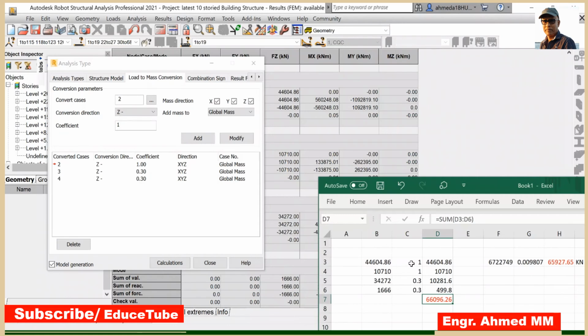This one is for self weight, this is for superimposed, this is for live load, this is for snow load. I took the reactions from the reactions table and the coefficients from here, multiplying and adding, I got 66,096 kilonewton.